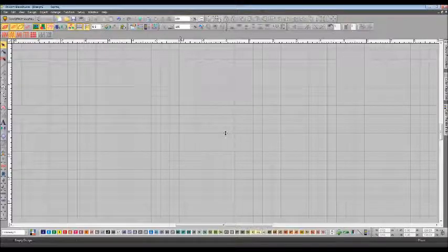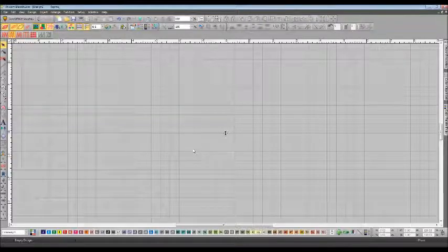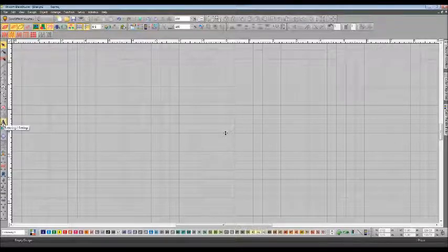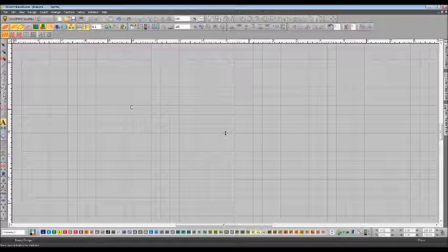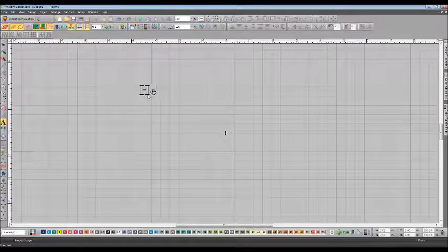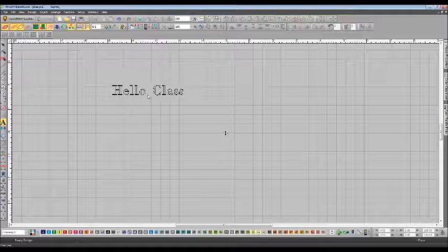Okay. So now we've talked about all this stuff. The first thing we're going to be doing generally in anything is going to be lettering. So we're going to talk about lettering first, and that will lead us into densities and all that sort of stuff. So if you left-click, there are two ways to enter lettering. By left-clicking, click on the screen, and you can just type.